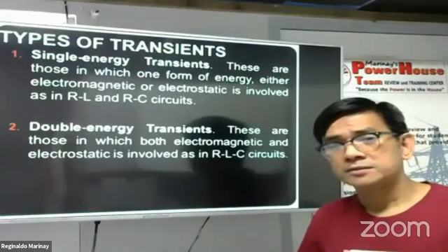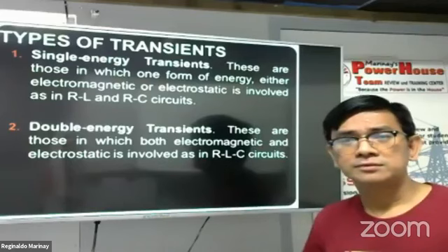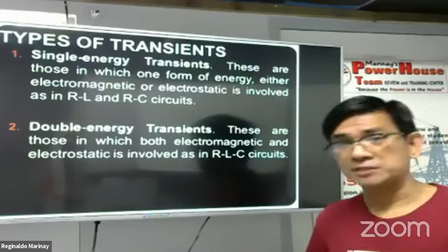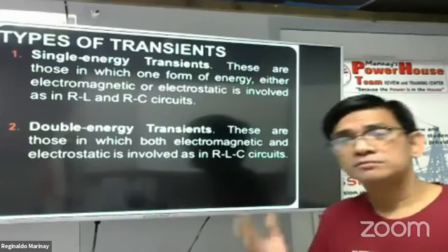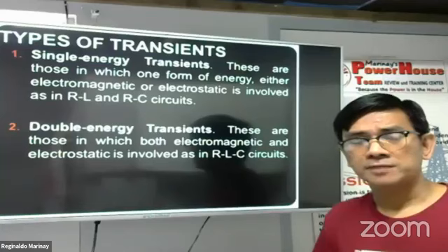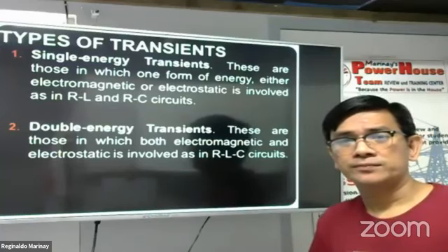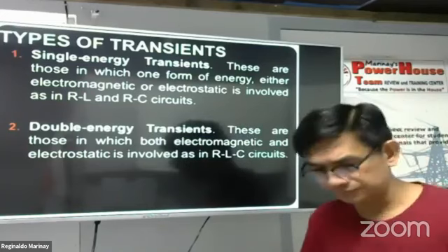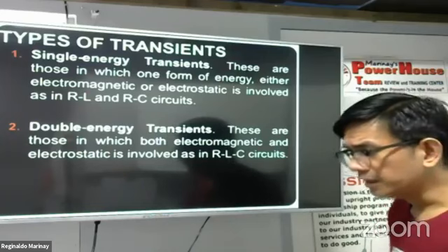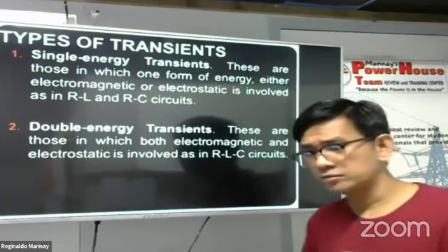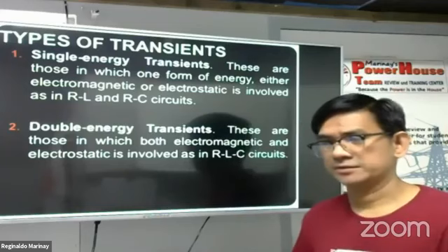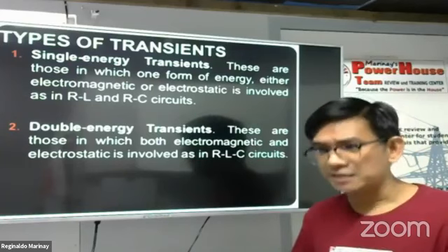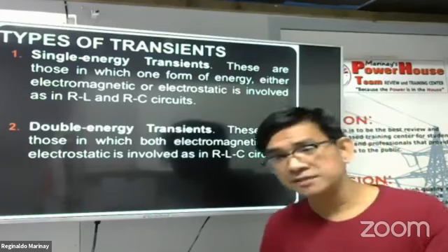As a remedy for this, as a solution, you better connect a capacitor because it is a reactive power generator. If you connect a capacitor, this compensates the loss. This lessens the loss, and the inductive power drawn by the load becomes lesser, because a capacitor generates a leading kVAR, a leading reactive power.